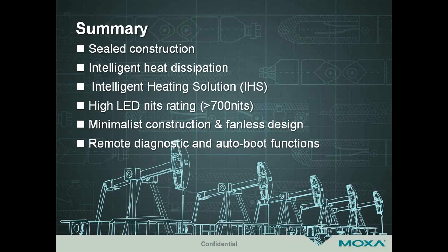That's changing. We're actually having the ability to have multi-touch functions with resistive screens. So the functionality that you like, say, with a dry hand on your iPhone or your iPad, will be possible in the future with resistive touchscreens. But that's the reason why: people in the industrial realm have to wear gloves, and there's a lot of things, whether it be sand, water, extreme cold temperatures, or gloves, that require resistive versus capacitive touchscreens.